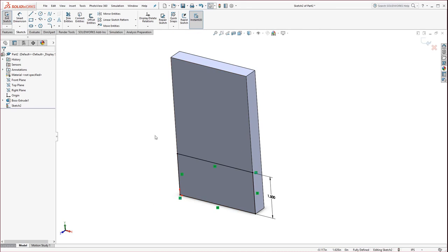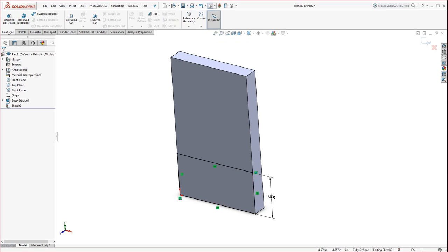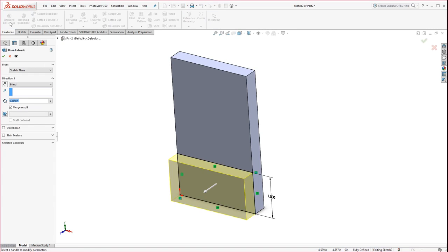Okay, so anyhow, now we're going to go ahead and we're going to extrude this. So if you remember, the Features tab is for the extrusions, or I like to call them the 3D tools. Brings us into the 3D world. Notice the object action paradigm and action here. It's actually activated a few more tools for us because now we have the ingredients needed to maybe use those, which we're not really going to use just yet, but just be aware we're looking just for extrude boss base again. Click on that.